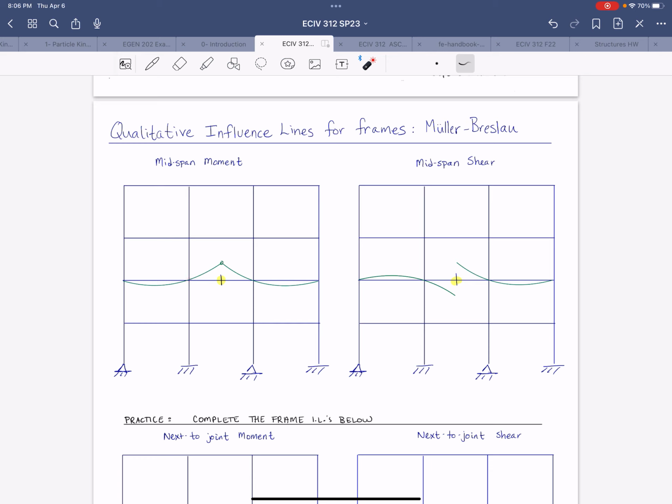When you do that, you can treat these joints between beams and columns as supports, all right? With the caveat that rigid joint behavior must be maintained. So that means columns have to sway, or rotate, by the same amount and in the same direction that the beam does. Right? You have to keep that 90-degree angle between beams and columns.